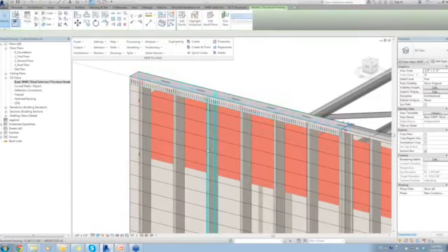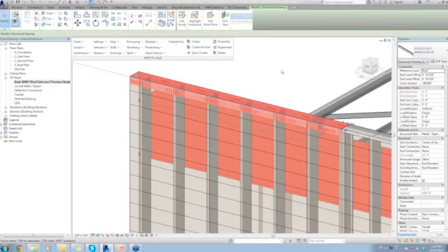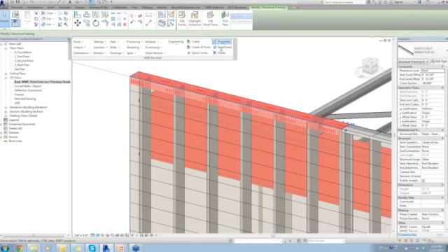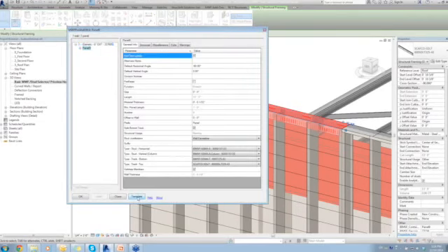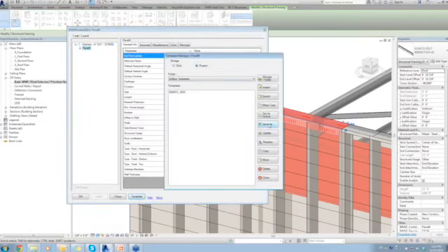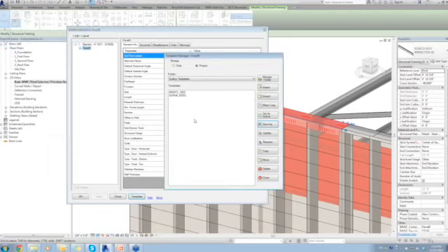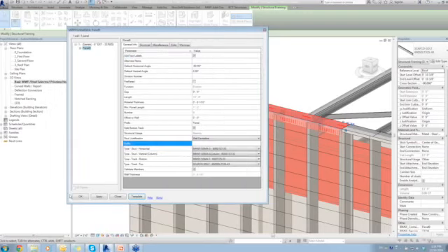So there you have it. I have the SCAFCO SDLT deep leg slotted track. And again, I can take this panel's properties and I can save it as a template. So this would be my exterior wall 600 deep leg. This template is ready to be used in future applications. So again, I can close this property down and continue framing my project.